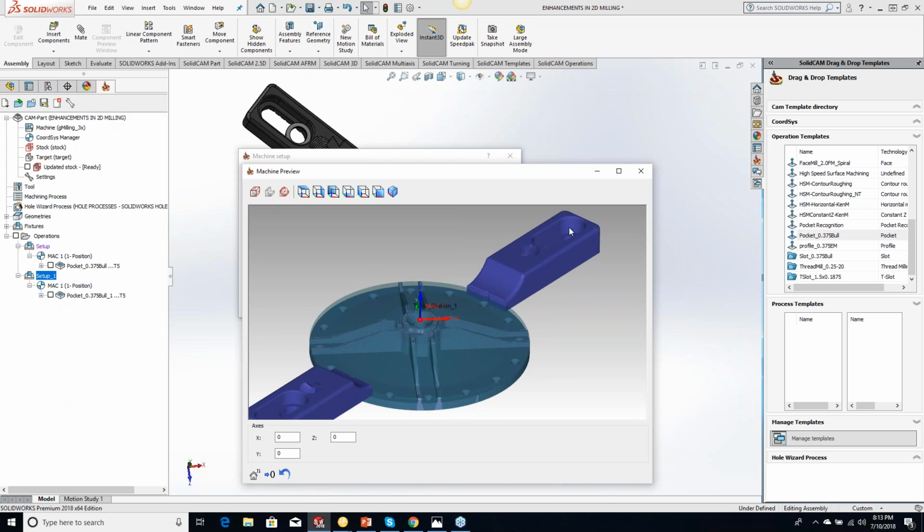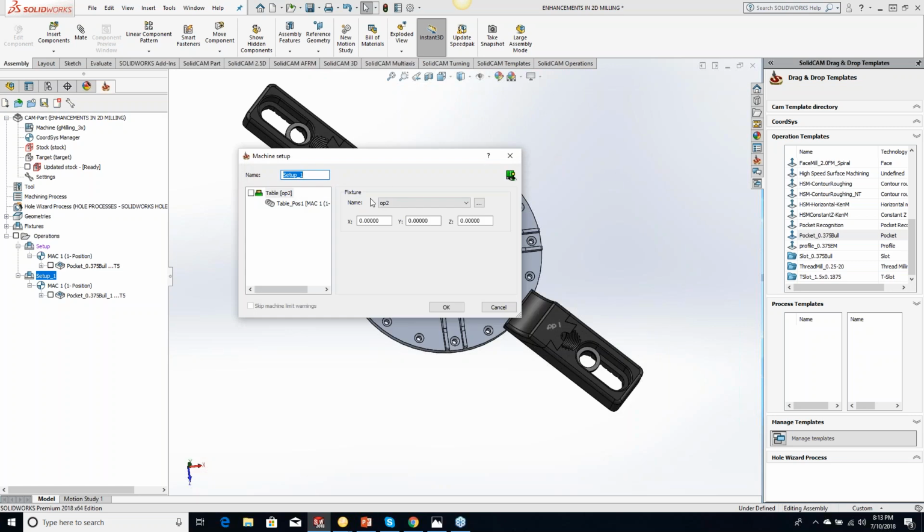No, the window before this one. This one. So you're looking for an on-off switch to kind of tie it together, like with a configuration, are you saying? Okay, yeah, great point. What Ronnie's saying is have a button right here so it pops through the configurations for us, and you guys could set your clamps up as op1, configuration 1, and then op2, and have a little button right here to switch back and forth. Yeah, great idea.